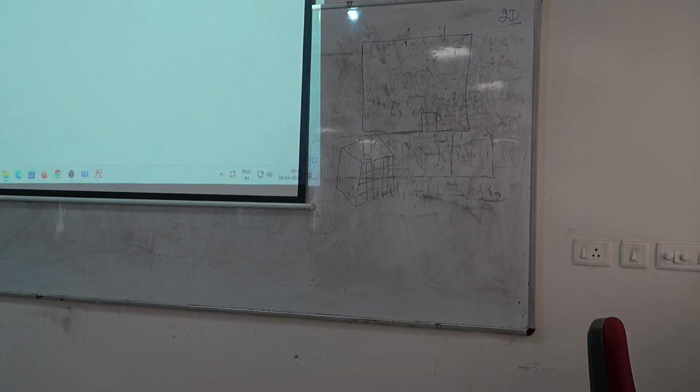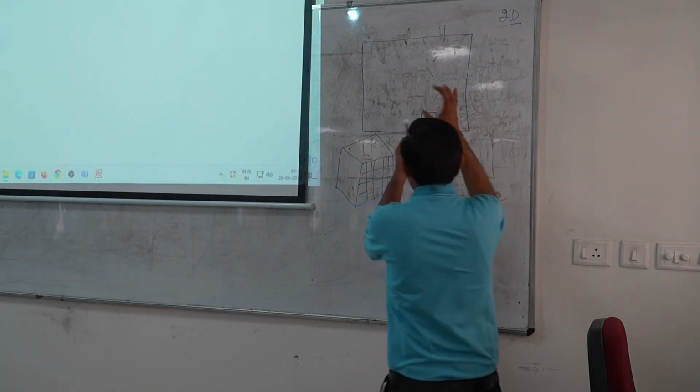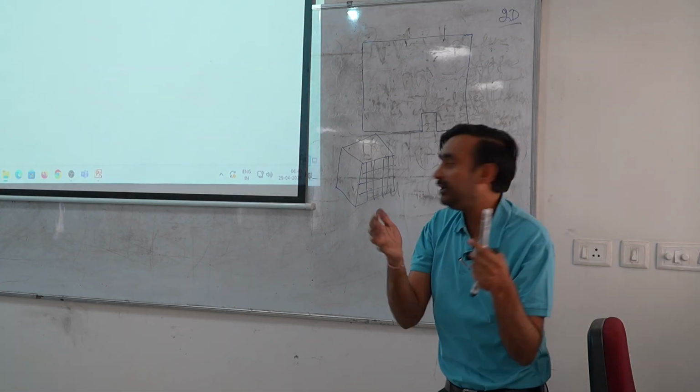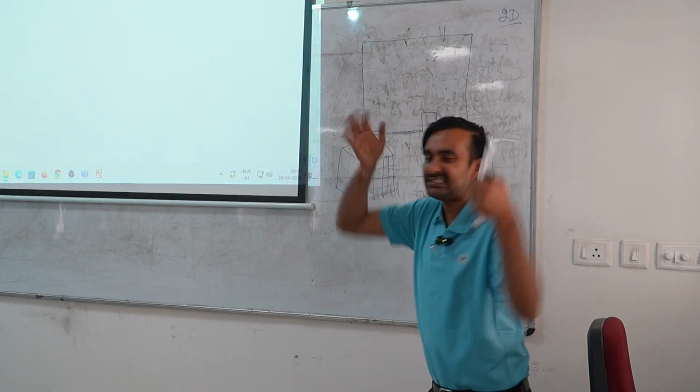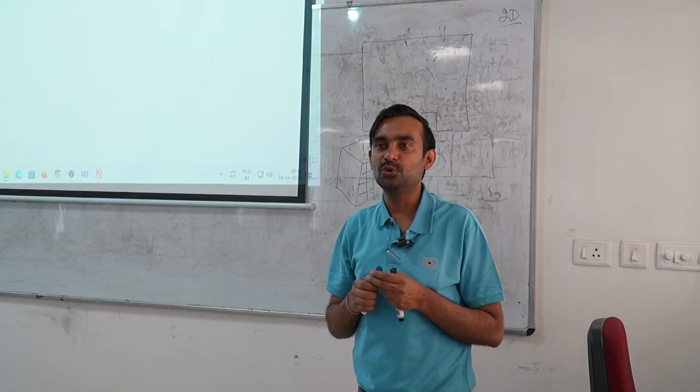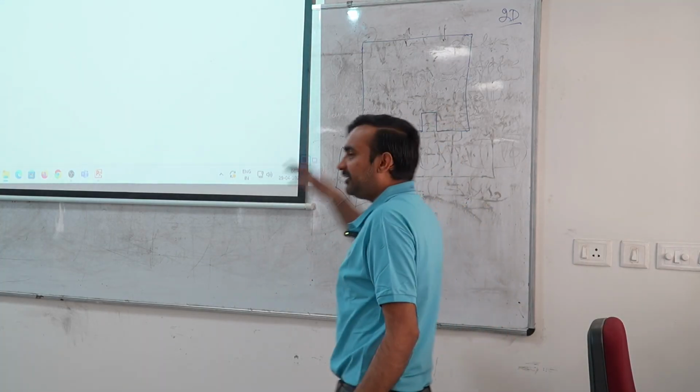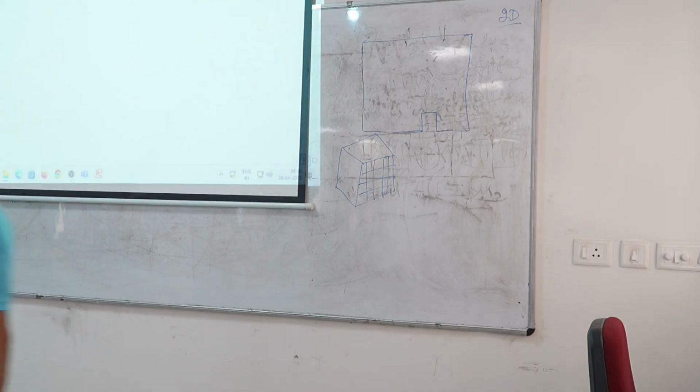Now, if you have this type of geometry and you can only use boxes to define it, what do I need to do? I need to split this geometry in such a way that the entire structure can be made using different rectangular boxes.